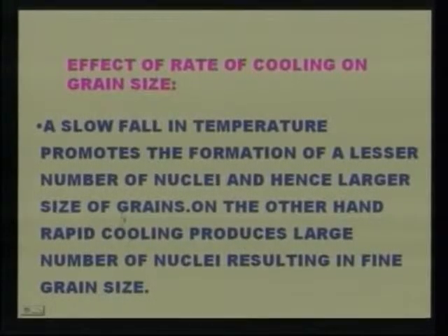As we have already discussed, slow cooling will help to form a lesser number of nuclei, therefore the size of the crystal increases, whereas rapid cooling restricts the growing of the grain size, therefore it creates more number of crystals in smaller sizes, which provides fine grain size.